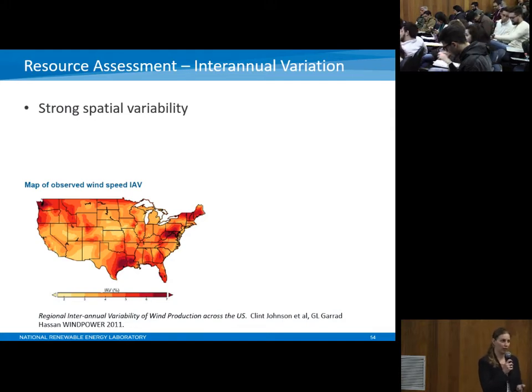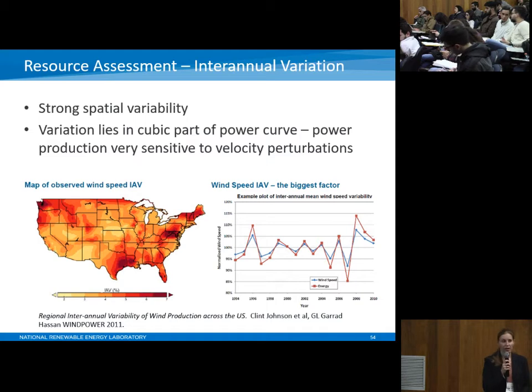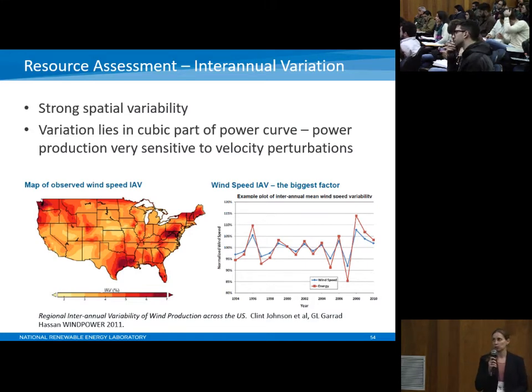How much variability you have in different time periods will vary depending on your location in the world. Because power depends on the wind speed cubed, these variations in wind speed have huge impacts on the potential performance of your wind farm. So you want to explicitly characterize the uncertainty around it as well as you can.